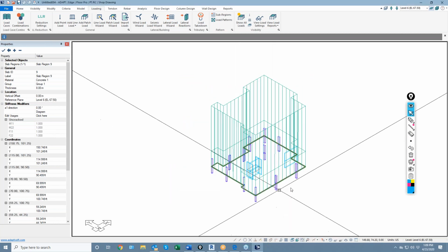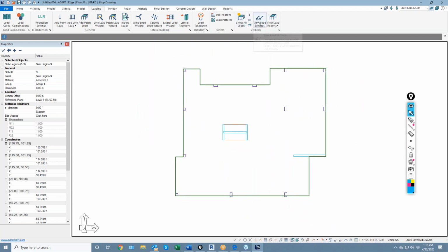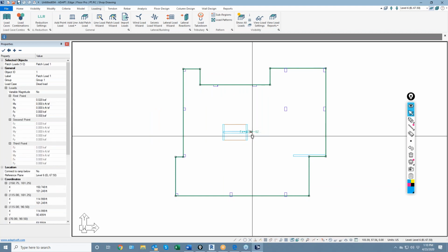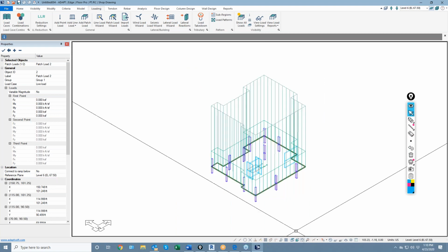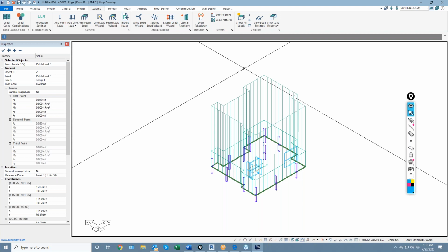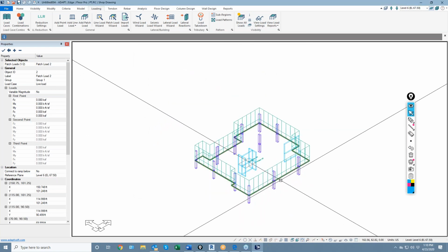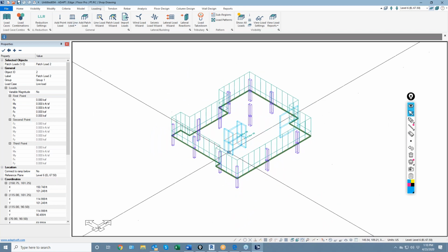And the loading, just very quickly, visibility wise, it's hard to see that in this view unless you come over here to the loading visibility panel, and we can go ahead and turn on, for example, the dimension of the loads, and then we can see those two loads are added and toggle between them, selecting that. From this perspective, we can see the loads clearly. If you don't like the height of that load symbol, we can change that, just change the symbol size here for the patch load. Patch load is the same as uniform load or distributed load in the model. So we have some loading there.